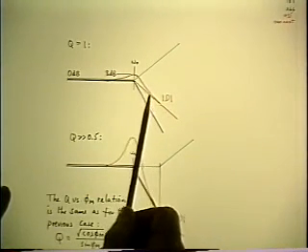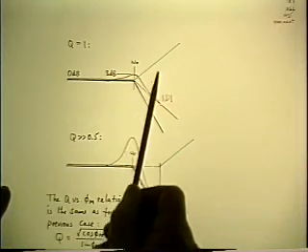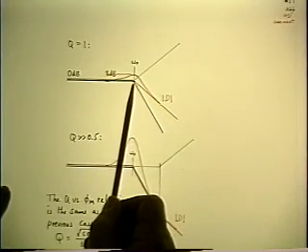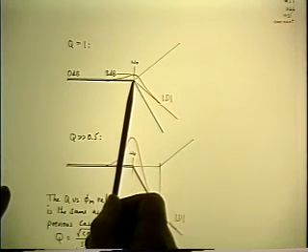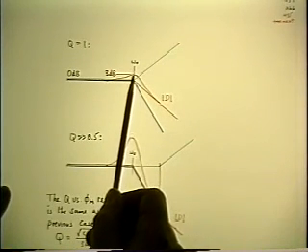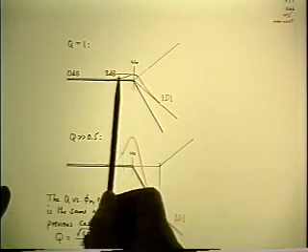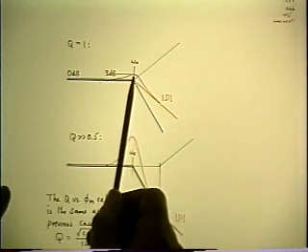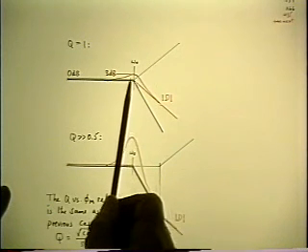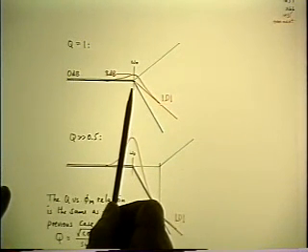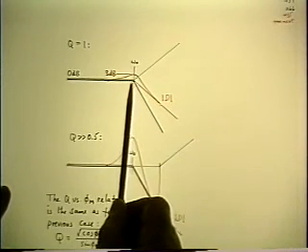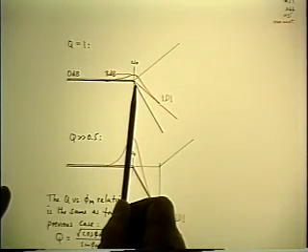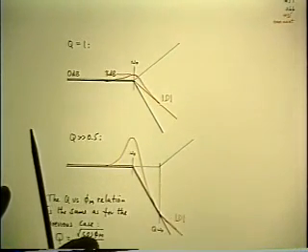So now the D is the sum of the blue and the green lines, and the blue curve will actually go through the corner, but the green asymptote will actually have a plus 3 dB point, the smooth corner that goes with the green asymptote. So the combination of the two of them will have a plus 3 dB point at the actual corner. So that's what happens when Q is 1 and the compensating 0 is at the original crossover. And already you see you get a 3 dB peak.